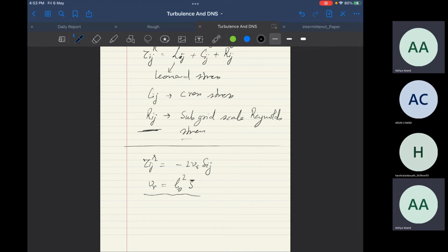Like you saw in that equation from that paper by Lizet on Incompact3D, there was a forcing term there, right? Likewise, we can have another forcing term for any other kind of body forces that are in the flow. The forcing term they showed was user dependent. They were using forcing when they wanted to enforce some kind of flow, and not using it when they did not want it. But let's say there is some physical phenomenon which says there will be some body force in the flow, then it will be part of that equation and it has to be solved.